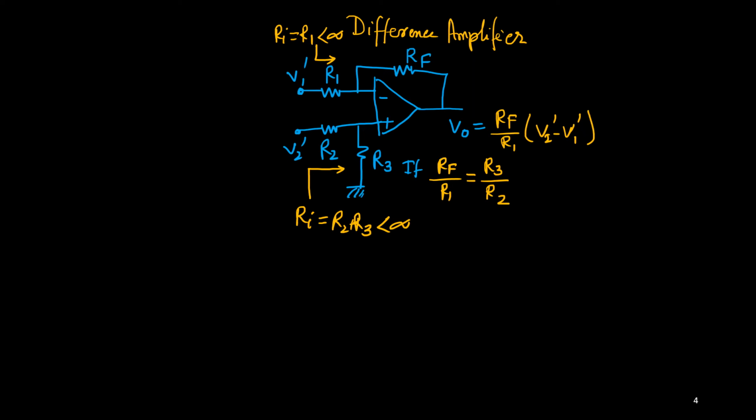So whenever you connect a bridge circuit, that bridge circuit will be disturbed. To avoid this, we can use one buffer circuit. That also we said in the last class. To isolate this bridge circuit and this difference amplifier, we need to use one buffer circuit. So a unity gain feedback circuit we can employ.